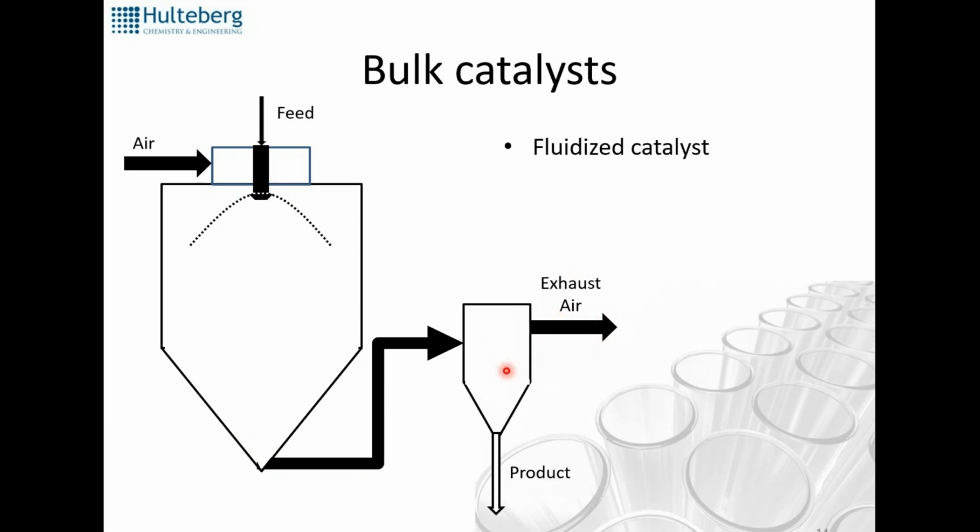And it's used for fluidized catalysts or any other catalyst where you have small particles, but it's also really, really good for handling these gels. So if you have a case where you form a rather severe gel where filtering is rather challenging or even impossible, then going to a spray dryer is a good alternative.